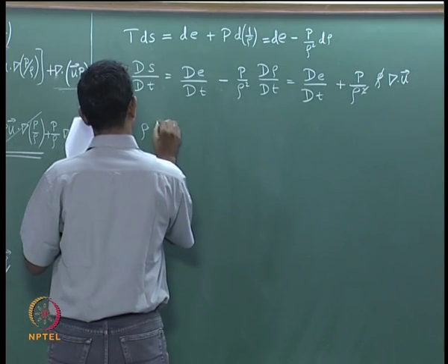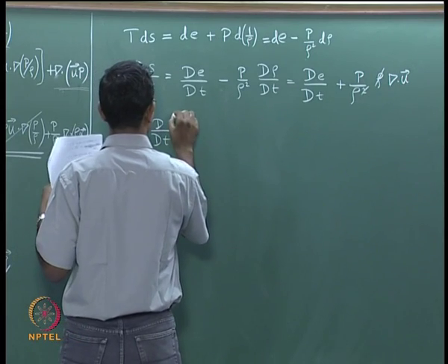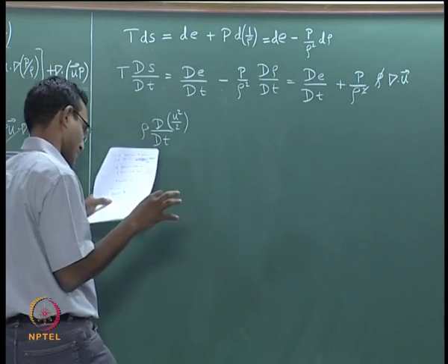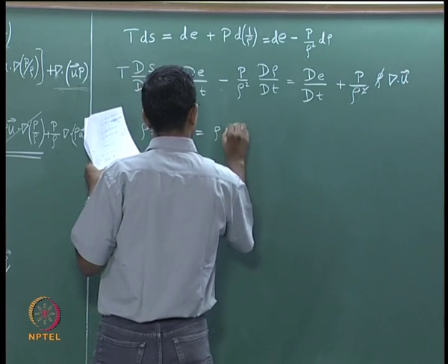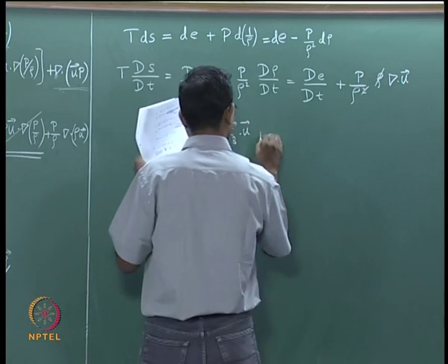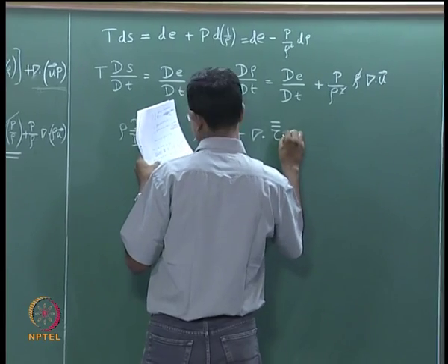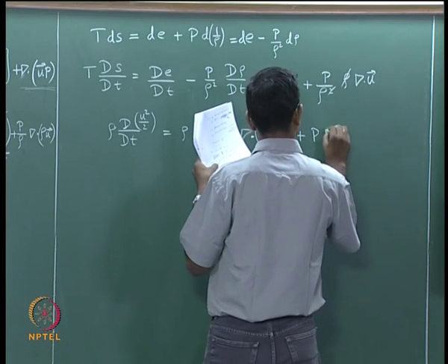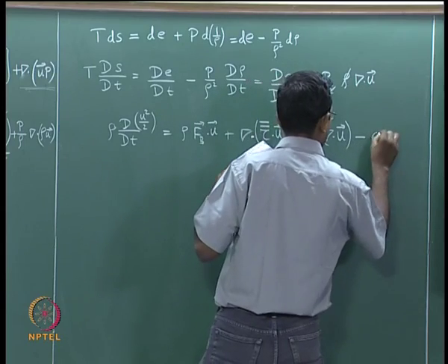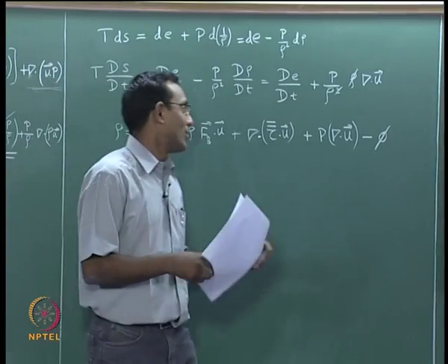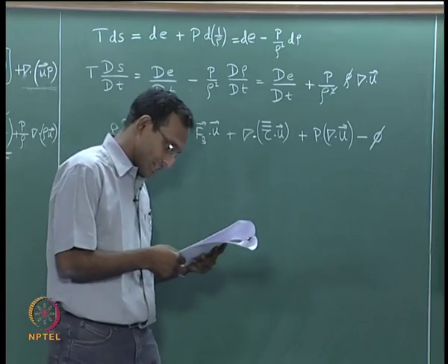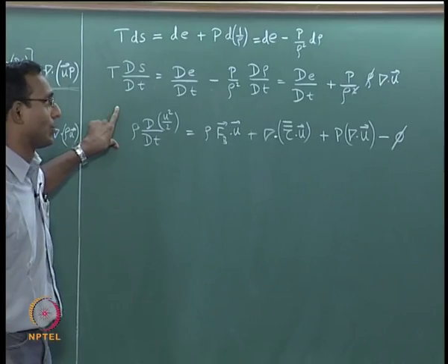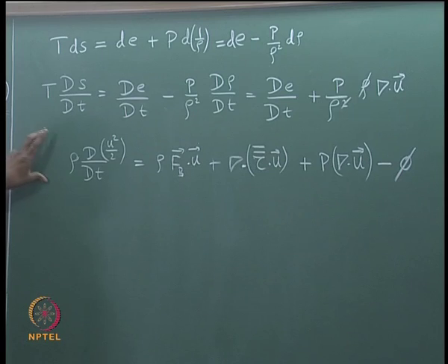Of course, this has again been simplified by using the continuity equation, so that density is outside even though it is used for compressible flows. I am putting u square by 2 because it is the kinetic energy form per unit mass basis. This term comes out to be rho f b dot u plus del dot of tau tensor dot u vector plus pressure times del dot u minus a term which I did not want to go into details of, but since it is in the equation I have to talk about it a little bit. That is called the dissipation of kinetic energy due to viscosity in this case. We have written an equation for kinetic energy conservation alone, where we did not talk about the internal energy of the gas, it is just that kinetic energy part.